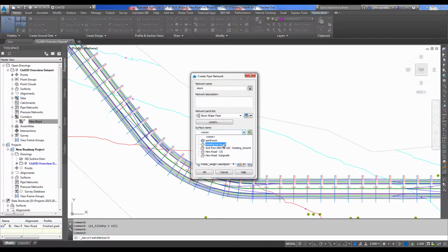We will have it stick the top of the structure elevations to our new road surface. We will have it read the new alignment. So whenever it gives a station and offset, it will show that inside of the label itself according to the horizontal control of the alignment. And we will just leave these two label styles set.